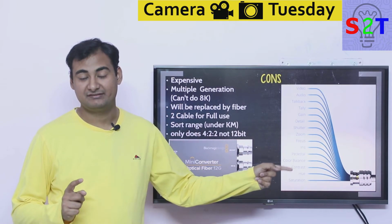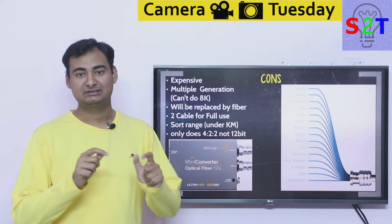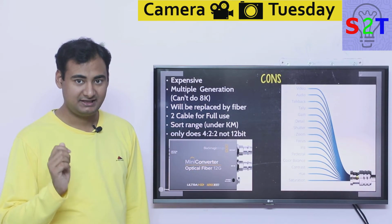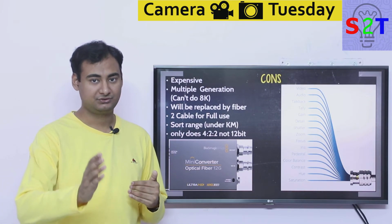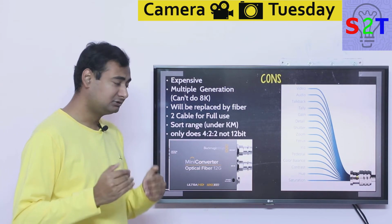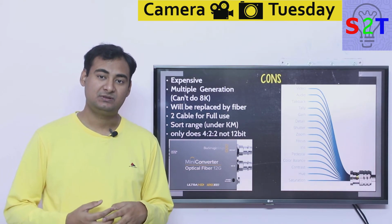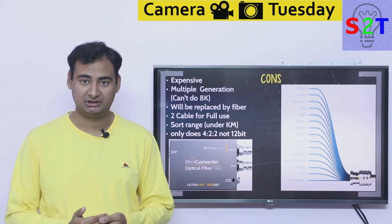However, it does come with a consequence. Even though all these things can be done, you need two independent cables. It's not that one big cable is there. You need two independent cables to do this. SDI basically has a pathway kind of structure. You have input and output, so that's why every camera that is good enough will always have SDI in and SDI out. Now, on top of that, because it was built for the broadcast industry, it was not built for quality. It was built for redundancy, it was built for quick operation, but it was not built for quality.